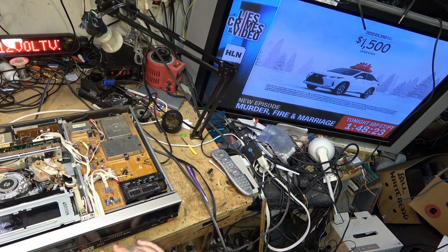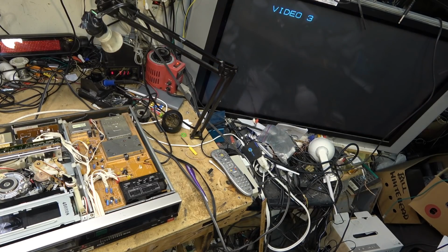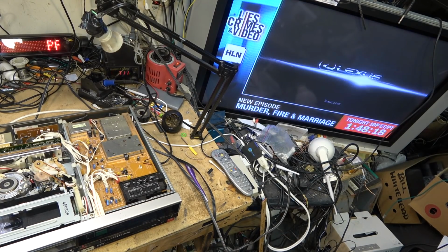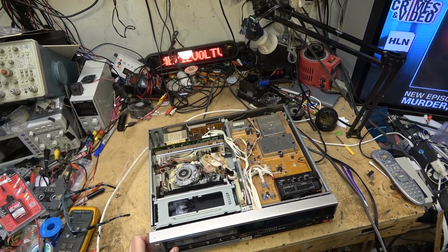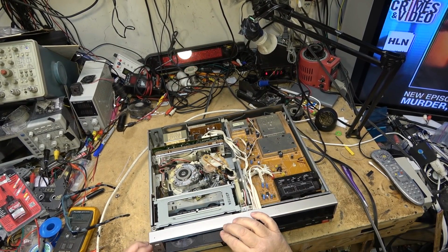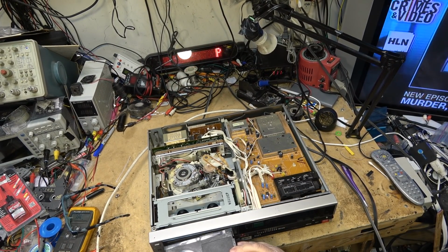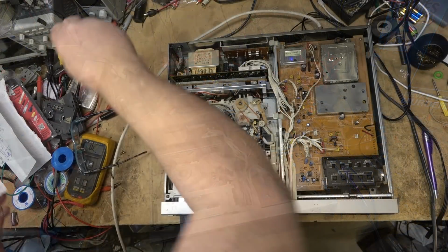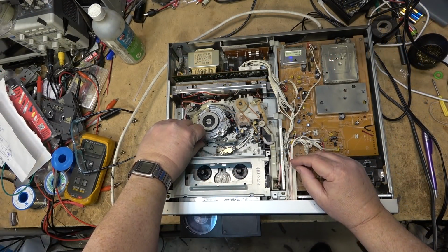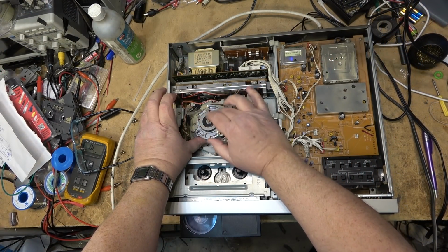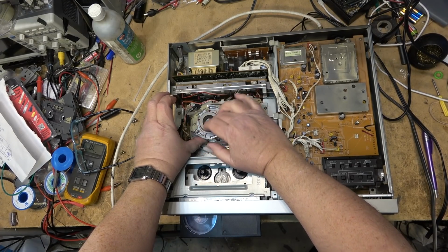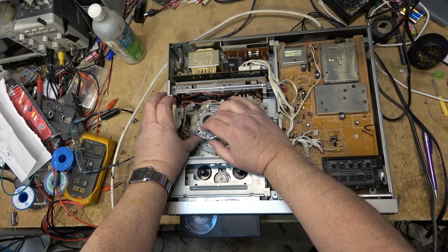We'll go back and we'll make a recording onto this beta tape. We're going to clean the heads first, so let's just remove the tape. We'll clean the heads, and then I'll do a recording on whatever this tape is. Let's get a piece of paper, hold it up against the head drum, and spin the head disc counterclockwise.